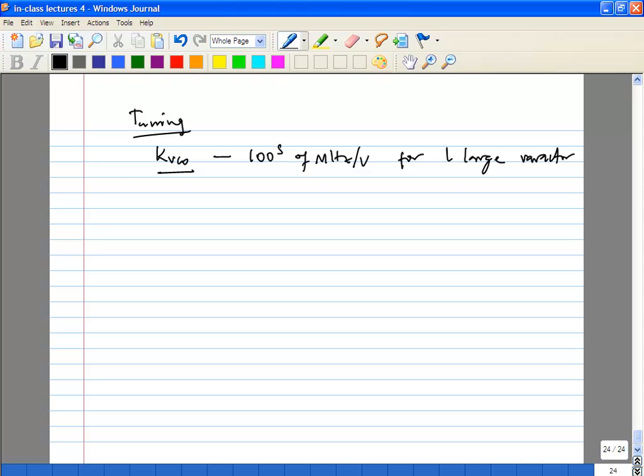So if there is, let's say, some current source noise, it has gone to the output as AM and then got converted through the varactor to PM, you will never see it. You will just see current coming from the noise, from the current source. You will be trying to change the sizes or the currents. You may not see a major impact. Okay, so you have to be very careful with KVCO.